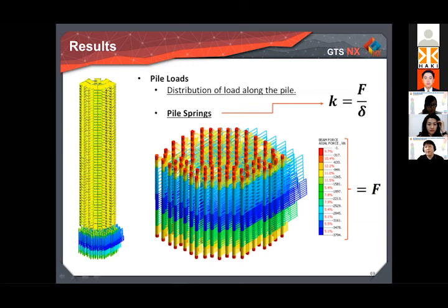This is a Piled-Raft. For area springs, the values of the pressure above the raft might be divided by the settlement at the same point. So this might also be sent to the structure team or exported to Midas Gen.